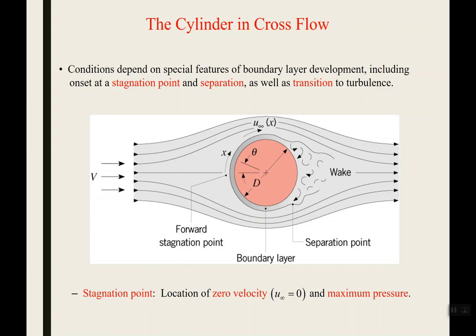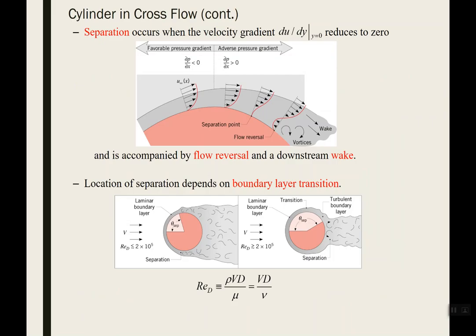So this actually becomes quite a bit more complicated than the flat plate, because now on the back side of this you start to get turbulence building up. The actual physics of this system is much more complicated, so we're going to go to purely empirical correlations here. But the Reynolds number we'll use will depend on the diameter of the cylinder. And again, this is totally different than flow through a pipe, because this is flow going around a pipe in cross flow. So while the Reynolds number is still defined with that very nice rho V D over mu, the value at which flow transitions from laminar to turbulent will be different.